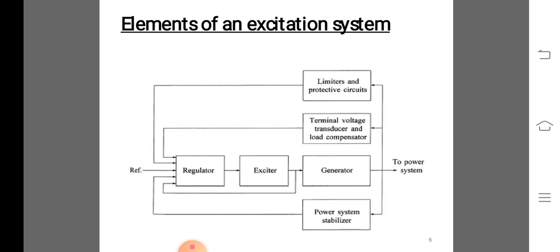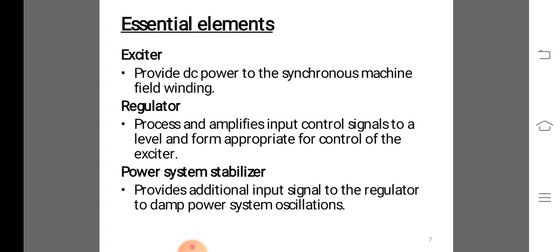In general, the present day practice is to use 125 volt excitation up to 10 MVA units and 250 volt system up to 100 MVA units. The units generating power beyond 100 MVA have excitation system voltages varying widely. Some use 350 volt and 375 volt systems, while some go up to 500 volt excitation also.